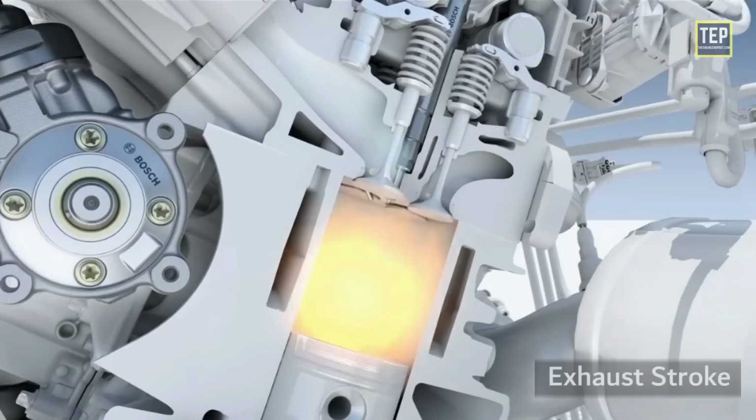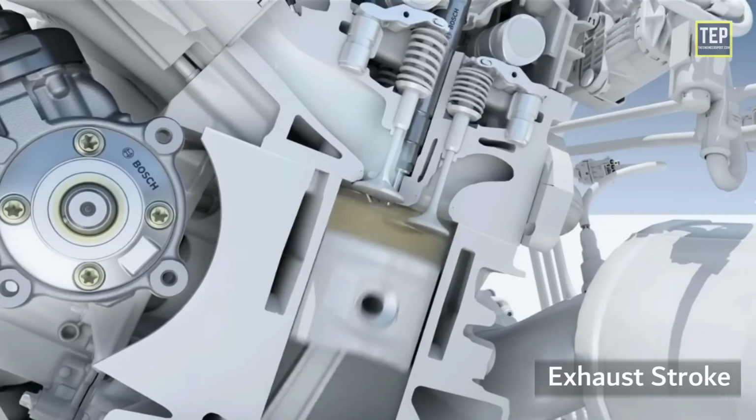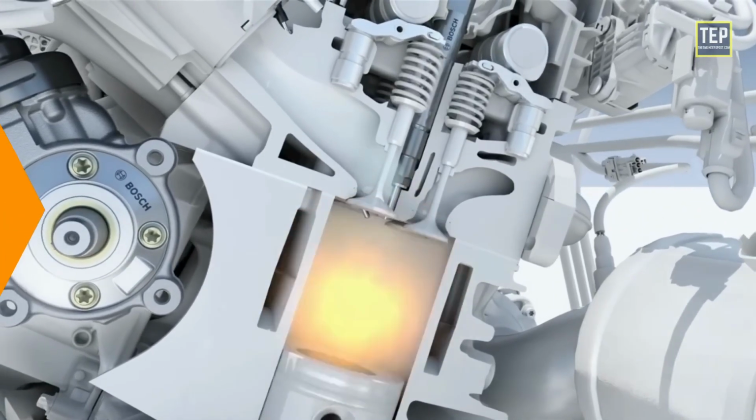Exhaust stroke. The piston reaches the bottom dead center and starts moving up. The burnt gases are being pushed out by the piston and escape through the exhaust valve. Before the piston reaches top dead center, the inlet valve is opened, and the cycle is repeated.